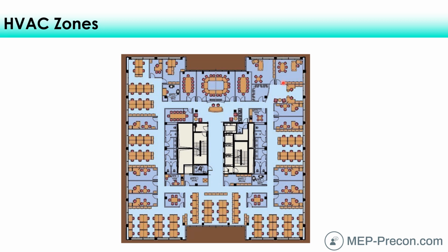That would have its own thermostat in there. So the number of zones correlates to how many thermostats you have. Each individual zone would have a thermostat that senses the temperature in that area, and then it just reacts with heating or cooling just for that zone. So it's a good idea to have corner zones have their own thermostat because they have 2 exposures, and it's kind of hard to accommodate 2 exposures when that thermostat is somewhere else perhaps.